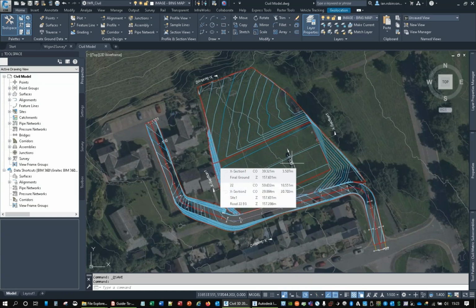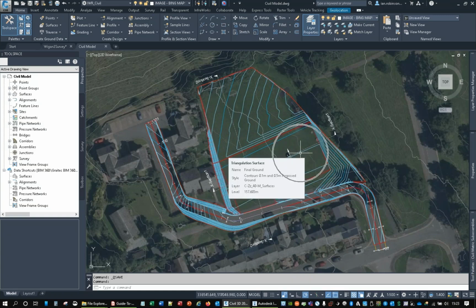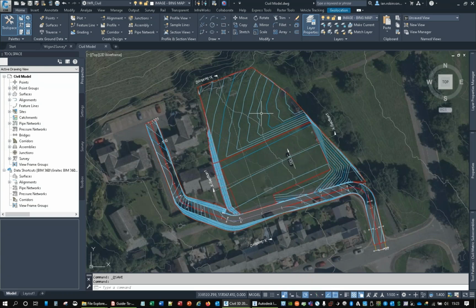Now, if we put this back into InfoWorks, what we can then do is we can put the car park into one surface category and put a style on it. And we can put the grass into another surface category and put the style on it. There is a little proviso which will become obvious in a minute. Now, let's have a look at what I've created here.